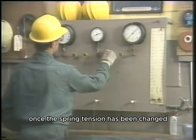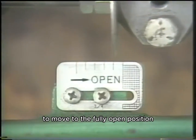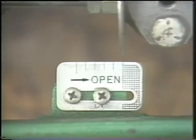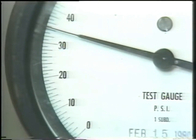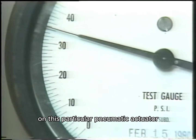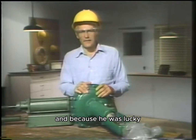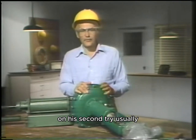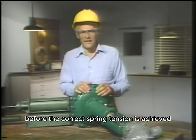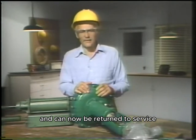Once the spring tension has been changed, he applies air pressure and allows the indicator on the stem to move to the fully open position. This time, the air pressure gauge indicates 35 psi. That's the desired air pressure at which the valve on this particular pneumatic actuator is supposed to be fully open. As a result of his experience, and because he was lucky, he was able to adjust it to the desired spring tension on his second try. Usually it requires a number of attempts before the correct spring tension is achieved. The actuator has been correctly adjusted and can now be returned to service.